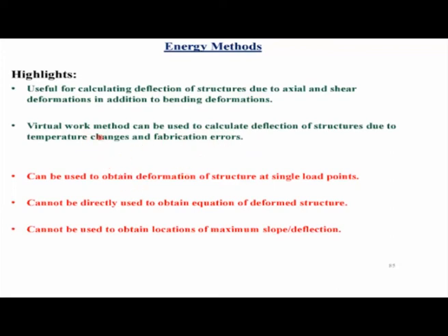But if you are using Castigliano's theorem, you can apply that load P as well as the external load simultaneously, calculate the internal moments, shear force and axial loads, which will be functions of load P, and then you can take the partial derivative. So in some cases it might be a bit quicker, or a little less elaborate than the virtual work method.